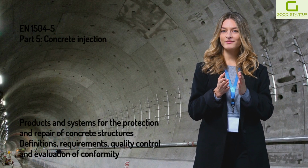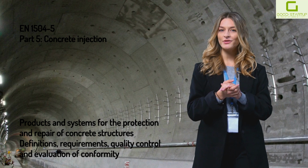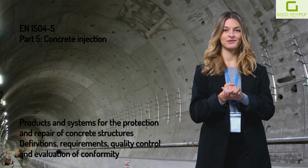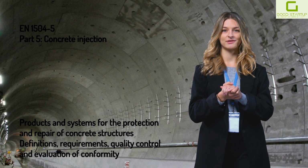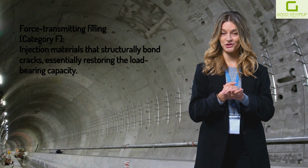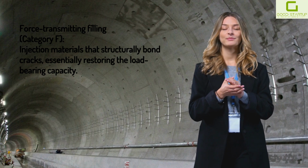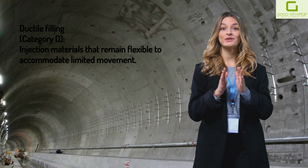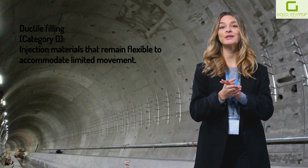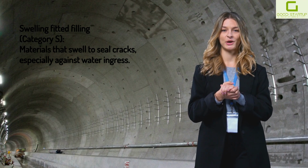EN 1504 Part 5 is part of the EN 1504 series on the protection and repair of concrete structures, and it specifically deals with concrete injection products. It defines three main categories of crack filling injections. 1. Force transmitting filling. Category F injection materials that structurally bond cracks, essentially restoring the load-bearing capacity. 2. Ductile filling. Category D injection materials that remain flexible to accommodate limited movement. 3. Swelling filling. Category S materials that swell to seal cracks, especially against water ingress.